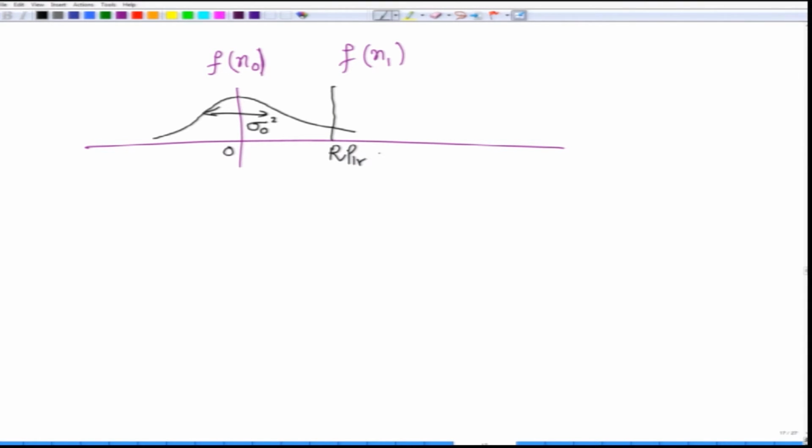Why is this so? Go back to Sk. Sk is equal to R P1r when you have transmitted bit 1. So, the received current Ik will be given by R P1r plus the noise component. And what is the average value of this Ik, which is obtained by operating the expectation on this one? Since this is a deterministic quantity, this would be just R P1r, okay, plus the expectation or the mean value of the noise voltage, but this is exactly equal to 0.